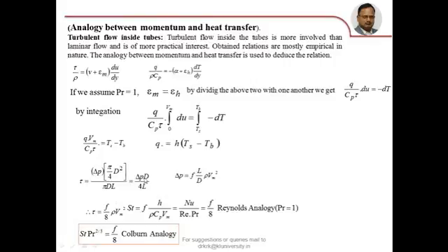So therefore, from this equation I can write tau is equal to delta P into area pi by 4 d square by pi dl, which is equal to delta P into diameter by 4L, where delta P is f L V square rho by d. So therefore, tau can be expressed as f by 8 rho v square.